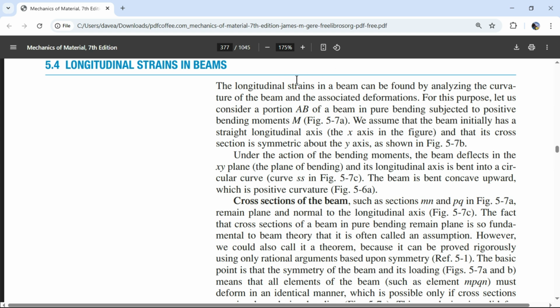Just for our problems or material mechanics, for steel, this number is really small. It's going to be 0.2%. But still, that ain't bad. We can visualize 1%. Now we're, decimals, fractions and decimals. It's really difficult to wrap your mind around fractions and decimals. So steel, the max change in length would be 0.2%. After that, you got problems.